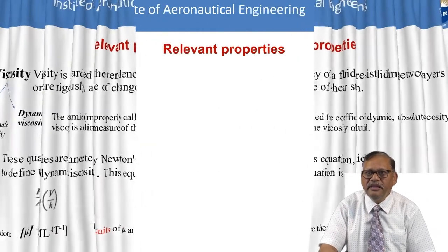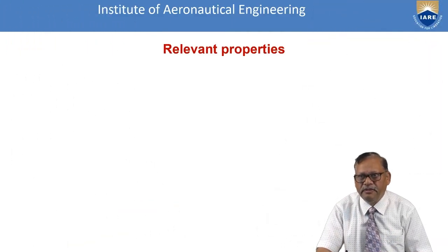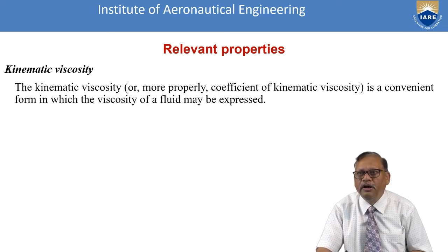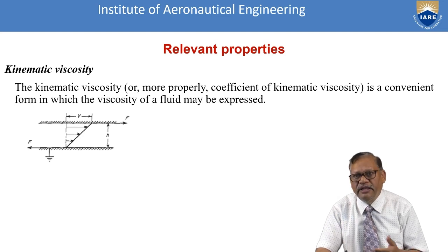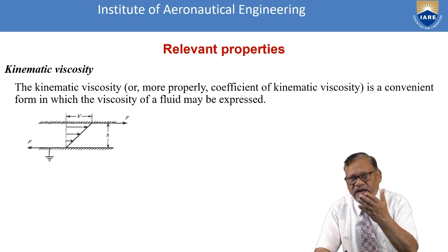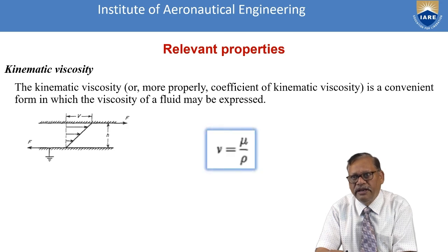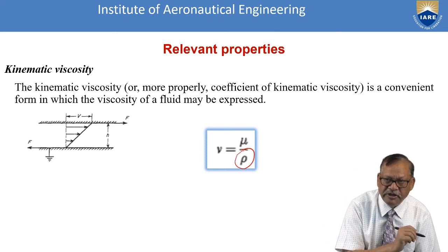Okay. And let us see the kinematic viscosity. What is kinematic viscosity? This is the definition we will use even more frequently than mu, and we denote it as nu. This nu is defined from the same quantities F, V and H, so nu is equal to mu by rho, the density. That is, the density also comes into the picture.